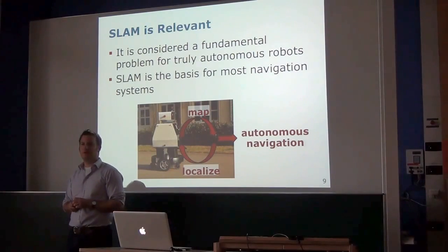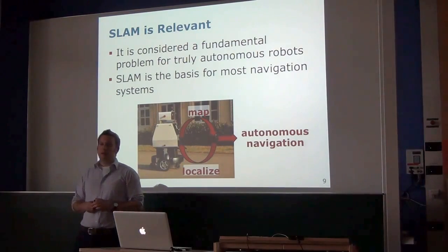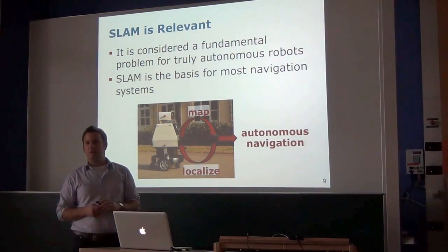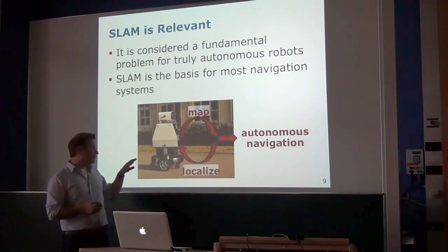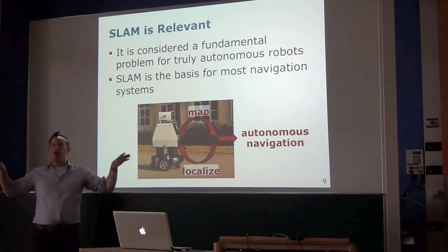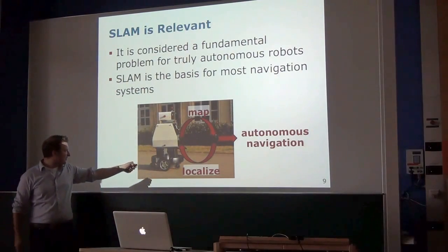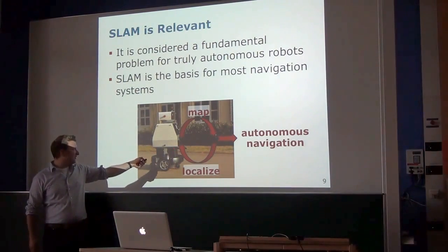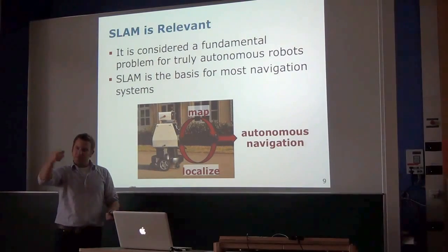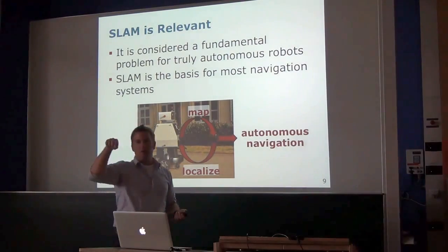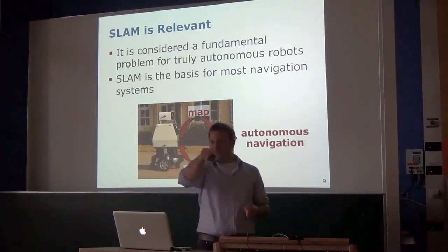Which kind of landmark did the robot use if it goes from checking and tracking? So in this system, we don't really use landmarks. We use kind of the raw scan data. So we use these kind of laser scanners. So one is sitting in here. You can barely see it. Another one is over here. They give you proximity information in the environment, and we use kind of the raw endpoint data, so we know just the distance to the obstacle.